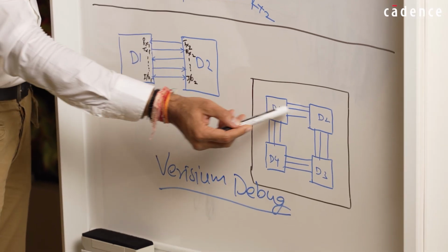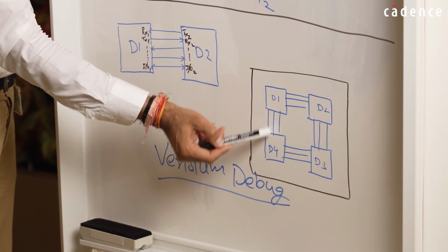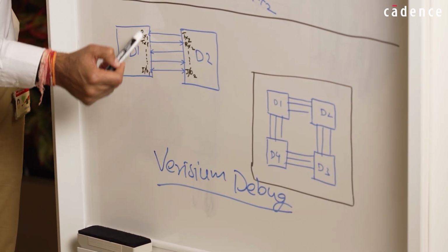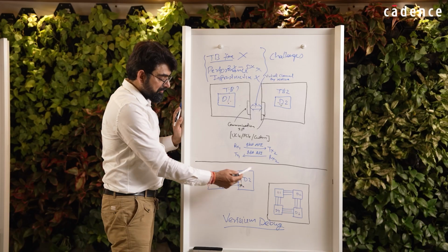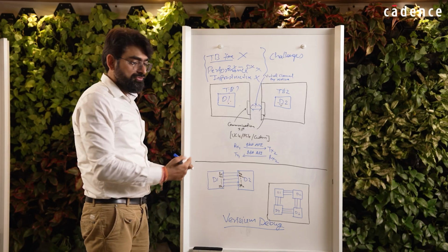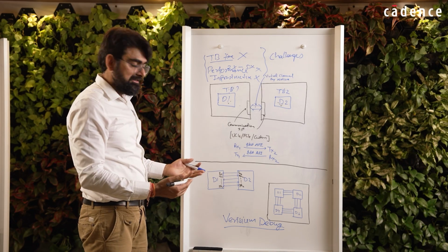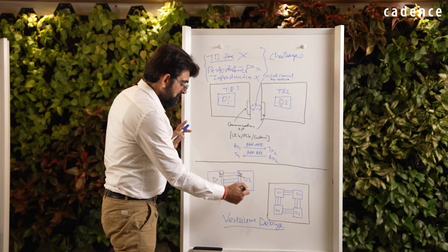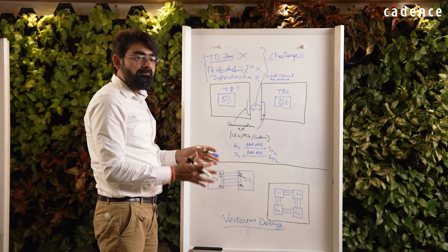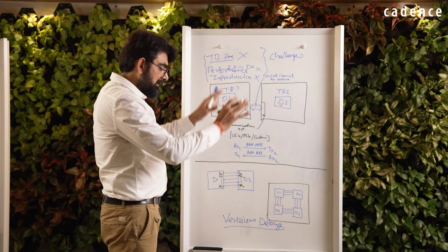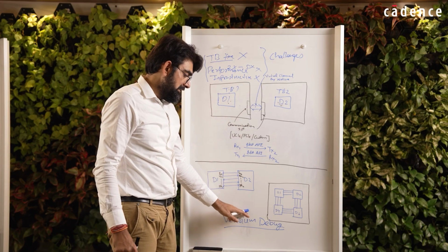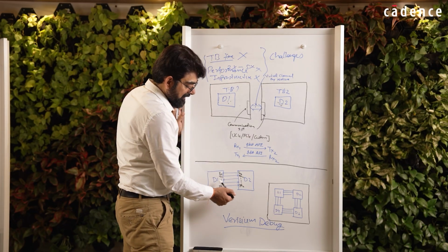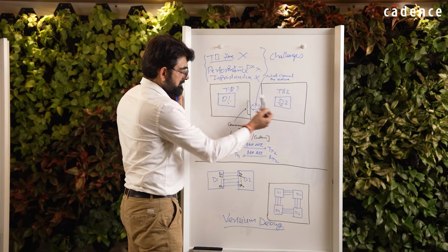And then if you want to double click on any corresponding two dies together, you can double click on it and it will give you all the signals that are connected from one to the other. So naturally, if there is any issue with your configuration, any mistake that you would have made inadvertently, you can easily figure that out. And because multiple databases can be flipped within the single debug GUI, one can even jump from one database to the other while debugging, as I mentioned here.